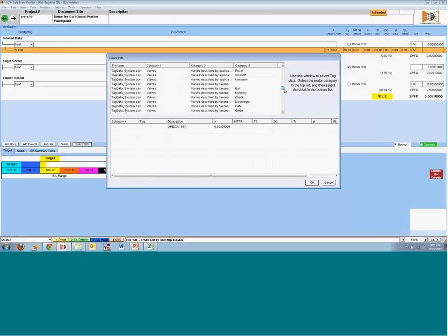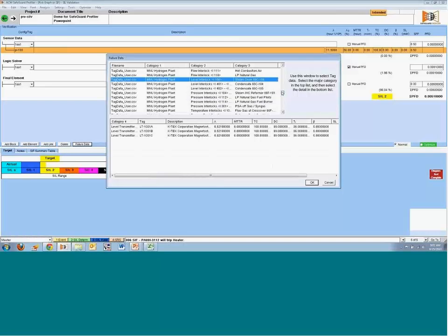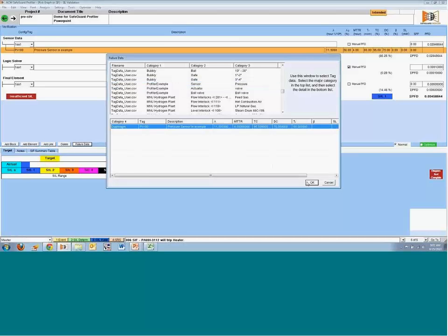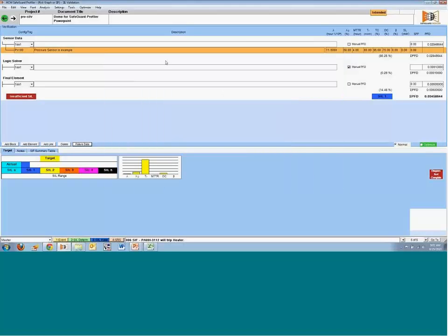As well, you can load in your custom failure rate database, which is going to be a comma separated value. Basically, it's going to be Excel. So we can look at some data that's been put in there, for example, for some real life information. The sensor here that I'm going to grab, that's all the information that was in my PowerPoint, so I generated that ahead of time. It automatically puts the information in, including the tag, and it's going to calculate your probability of failure on demand.